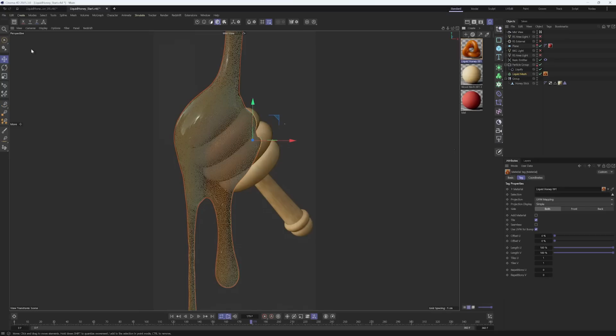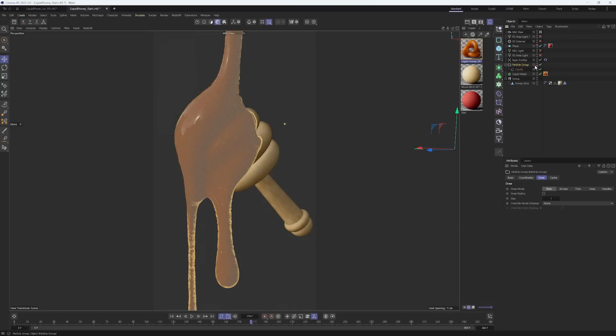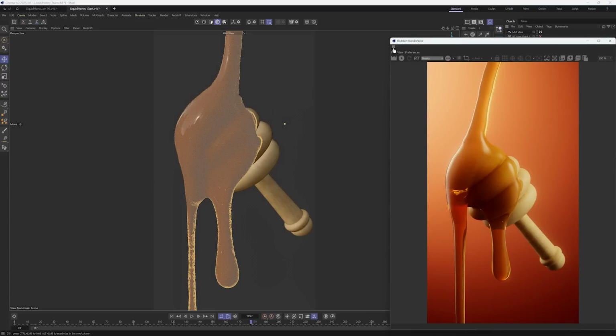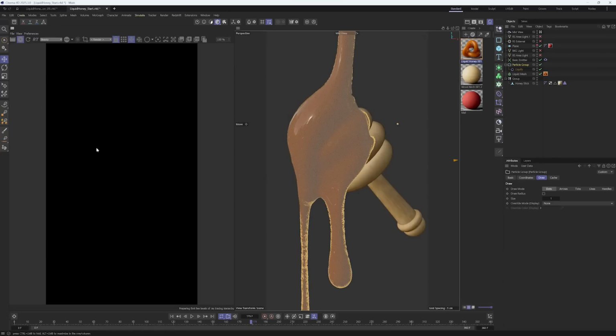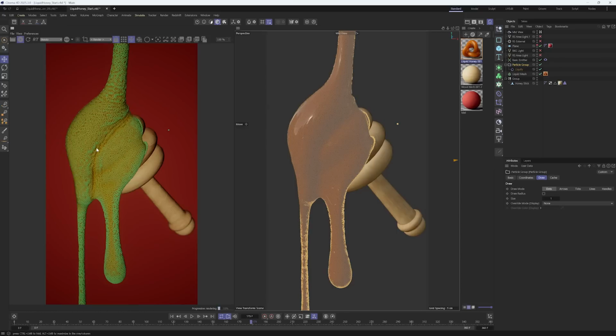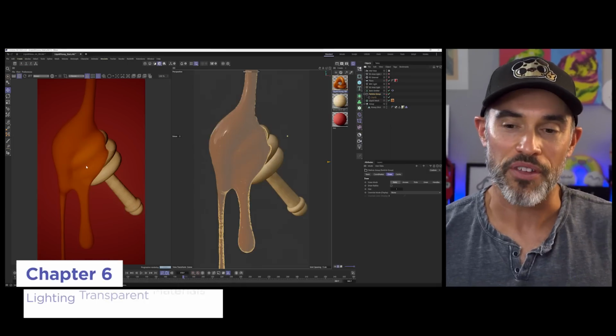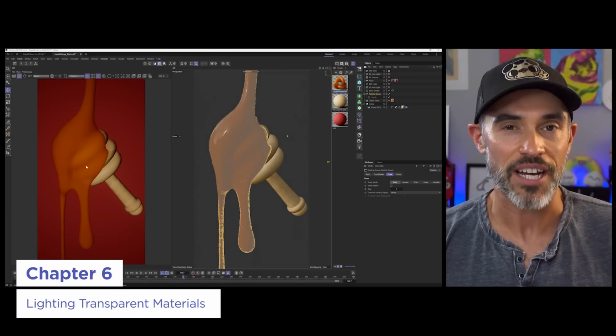So I'm going to go and close out of our asset browser. I already turned off this particle group from render. So if I go and get my Redshift render view and then dock this to the side and fire off this render. And again, you can check out this project file and all of the different post effect settings that I added into this as well. So again, if you don't turn off the particle group from render view, it's going to show up there. So we'll turn that off. And so what we're left with is an unlit scene that looks kind of garbagey.